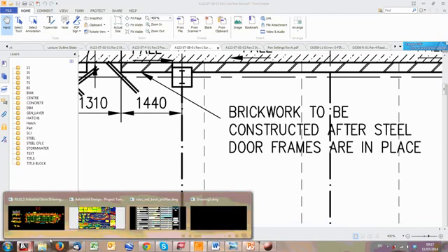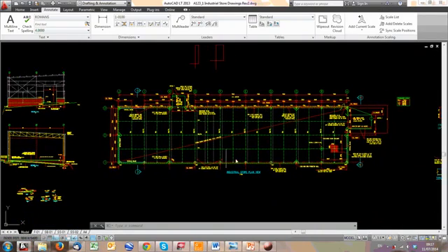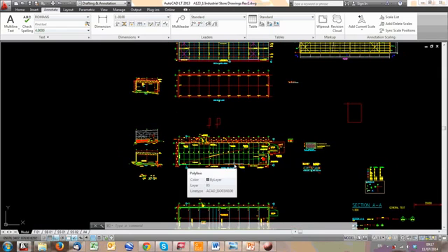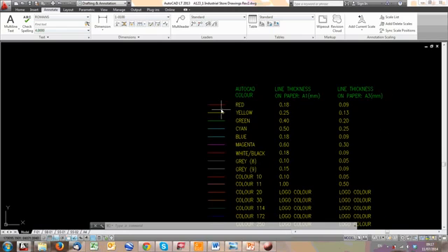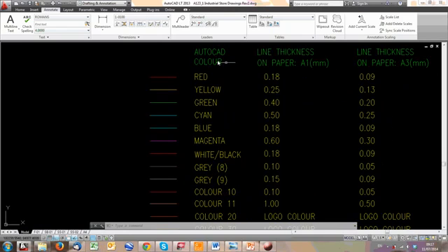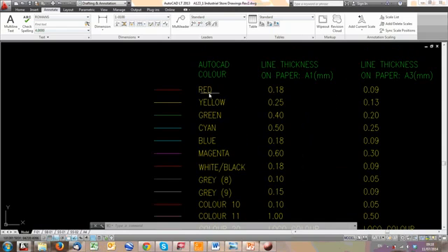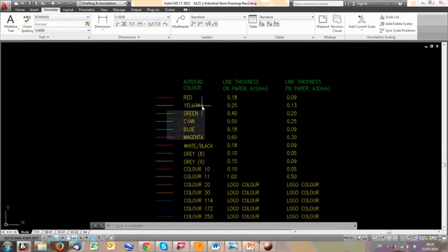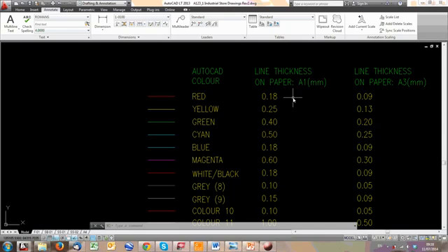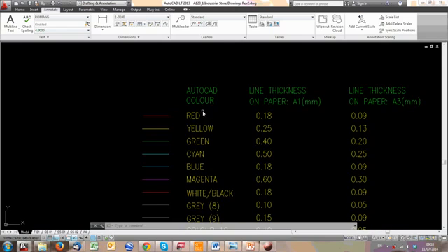And you do that by using certain colors and mapping those colors to a thickness. Because in AutoCAD, what you do is you set up something called a CTB file, and that pen setting style maps a certain color to a line thickness. For instance, these are the colors for the specific CTB file we're going to be using now. And each company, or each discipline, will often have their own CTB file. So just be careful. My red might be thin, but for someone else, red might be thick. So just be careful when using details and drawings from one person's drawing for someone else's drawing.